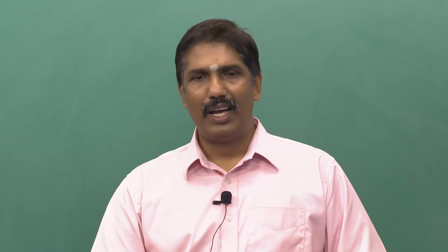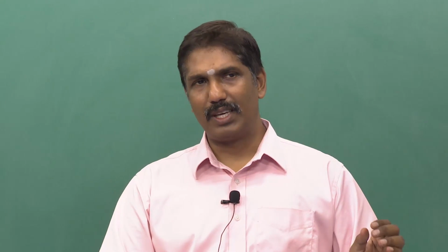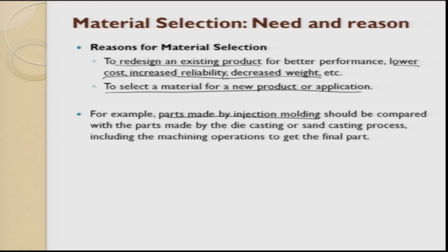So basically it was initially cast iron, from there they went into aluminum, lightweight, high strength, and mass production, batch production was done. From there they are now trying to move to the injection molding process, keeping polymer there, reinforcing with carbon fiber, making it light and high performance, so that they can deliver better performance to the customers. So for example, if you have a wheel rim to be made, this can be made out of the three choices.